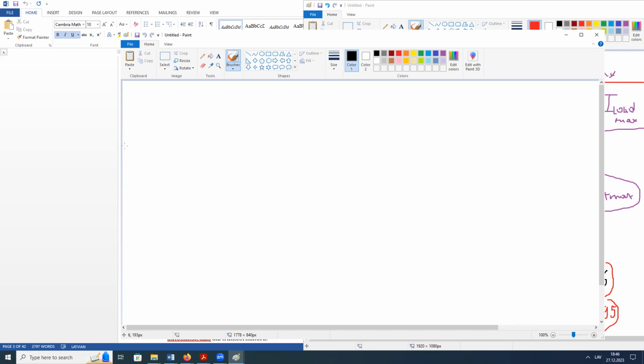So what does unsymmetric mean? We have two faulted phases and one not faulted phase, yeah? So this situation is unsymmetric. And in this case, how can we use the math to calculate this condition? To do this, there is a special theorem where we divide the network into three parts: the so-called positive sequence, negative sequence, and zero sequence.